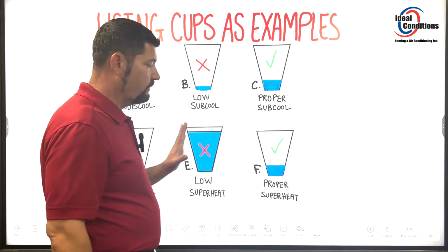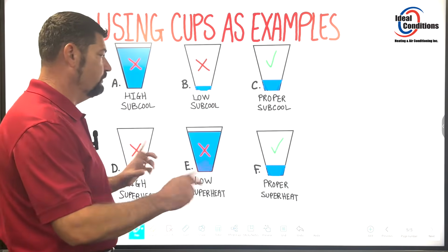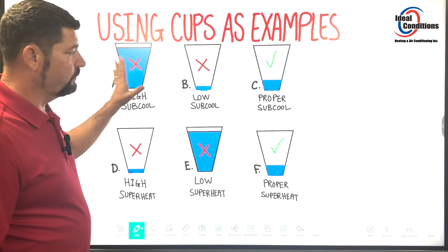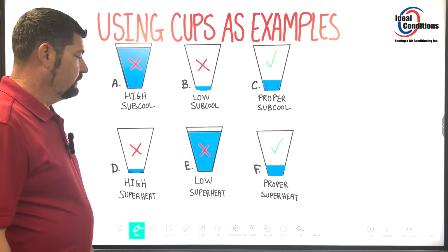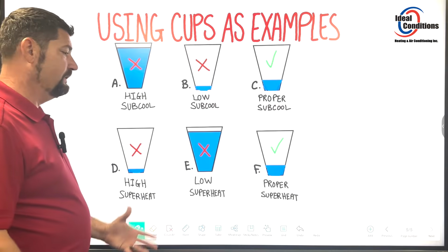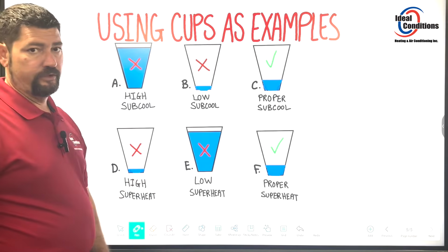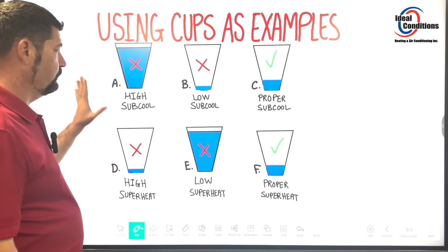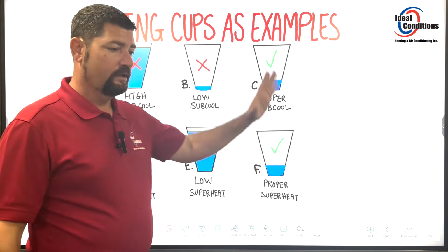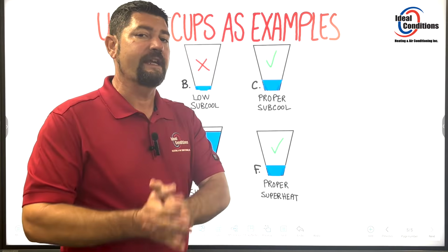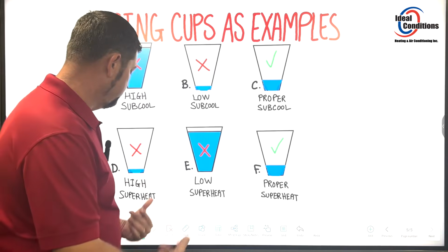And it doesn't matter what refrigerant I'm working on, because we're talking about the liquid and vapor ratios, right? So you can put 407C up here, 410A up here, MO99, 454B, R32. It doesn't matter what refrigerant you want to use. We're not talking about pressures. We're not talking about temperatures. We're just talking about liquid and vapor ratios, and that will never change when we're dealing with high temp. All right, so exploring this,